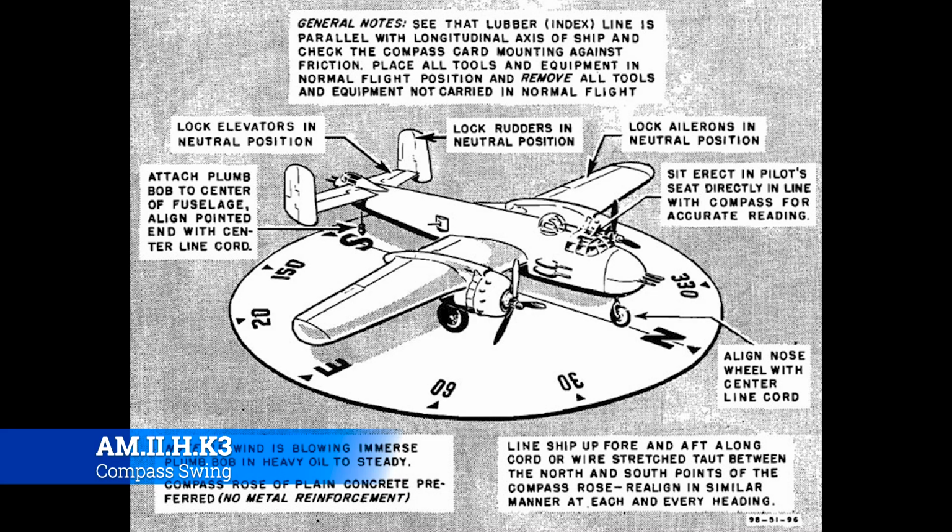Okay, we should talk about that. The aircraft interior and baggage compartment should be free from miscellaneous items that might interfere with the compass. So in other words, don't put your boom box back there playing music as you're doing this, because it'll throw it off. Anything that's magnetic, like golf clubs back there, could potentially throw the magnet in the compass off, so take those out. A good rule of thumb is just don't have anything in there, and you don't have to worry about it.